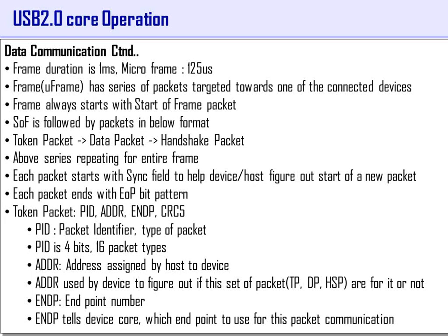So my laptop knows that if I have to read the keyboard, it has two endpoints, endpoint 2 and endpoint 3, let's say. To read the data, I need to generate a request on what? Endpoint number 2, because endpoint number 2 is the in type of endpoint. It knows because it did what? Enumeration on all the devices. It knows that information. From that, it creates the frames. If it is, let's say, endpoint number 3, which is in.